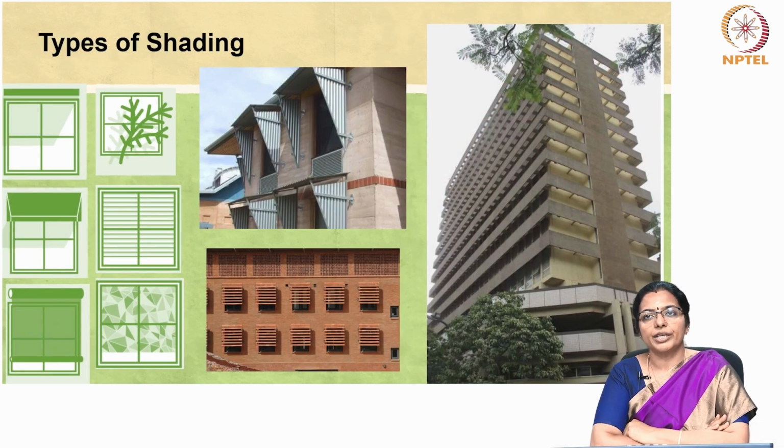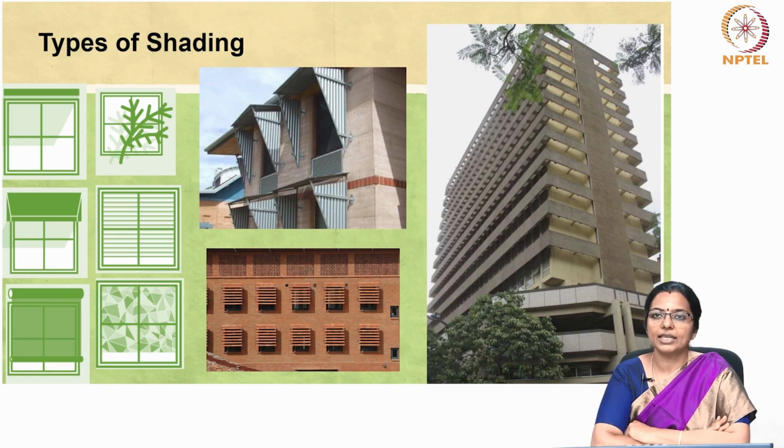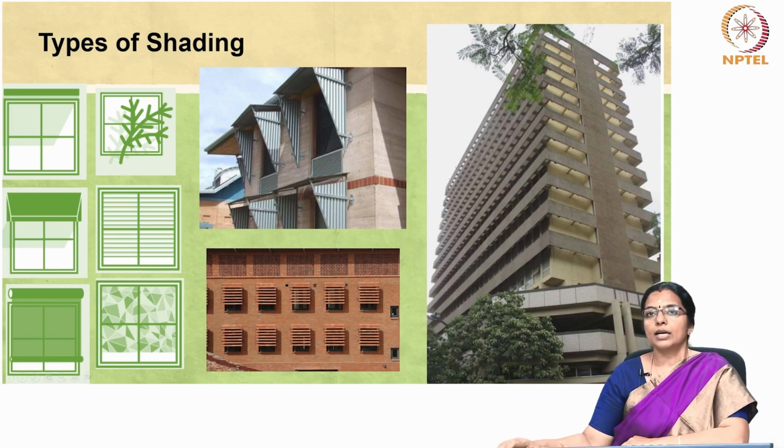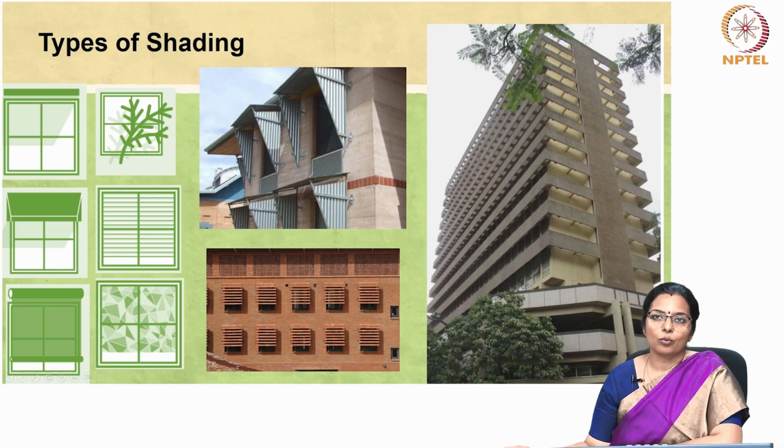External shading devices must align with wall orientation and building location to determine when shading is required daily and annually, as well as the angle of solar radiation. Shading masks, a graphical representation of shading, aid in designing effective shading strategies. Some of the types of opening shadings are overhangs.